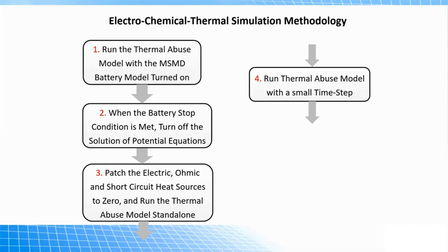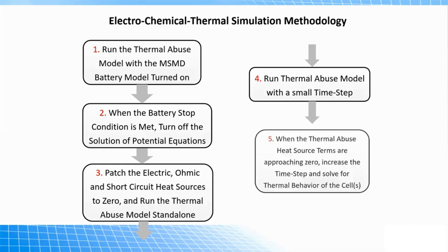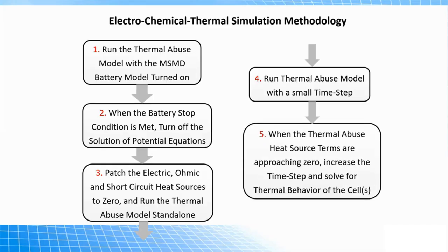The next step is that you run the thermal abuse model with a small time step. And finally, when the thermal abuse heat source terms approach zero, you can increase the time step and solve for the thermal behavior of the cells.